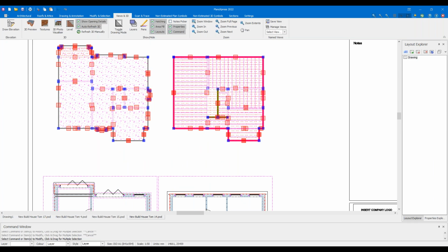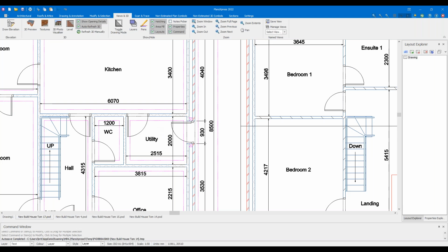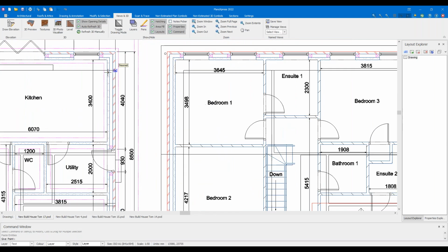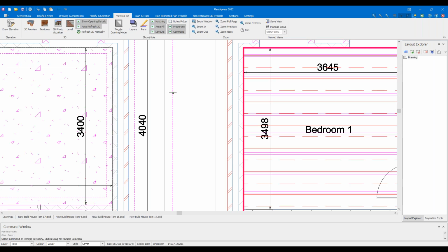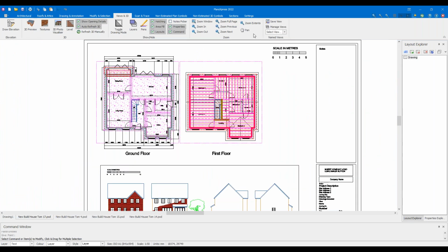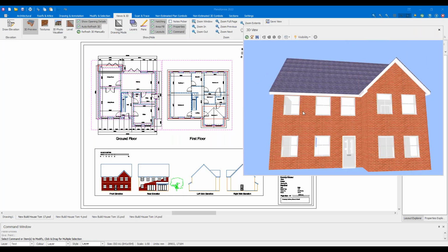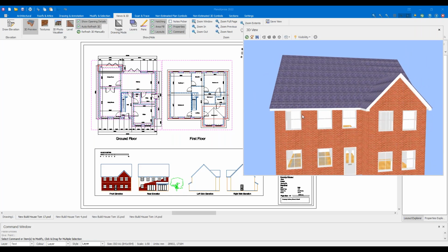So I'm going to copy that, go to my house 17, and place that in there. There we go. I can do all I think to set floors and ceilings and go back to what it was. But now if I look on this one, floors are back. Yay, fixed. So sometimes if you copy and paste something to another page, you forget to show the floors, and you might have to go back to a previous one to grab it.